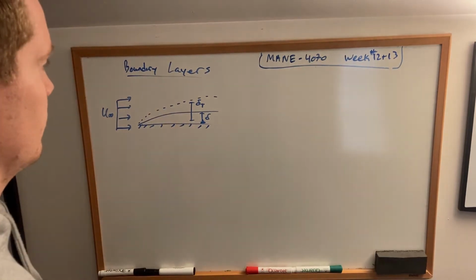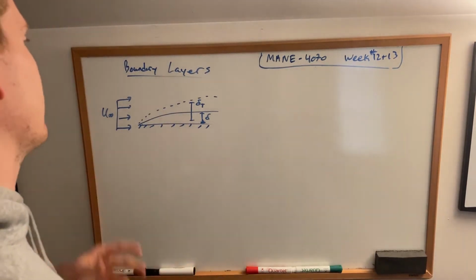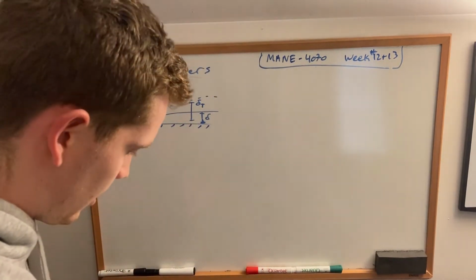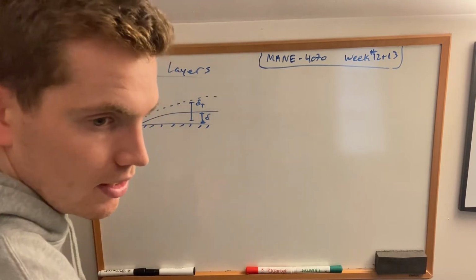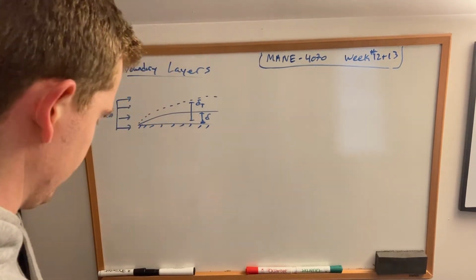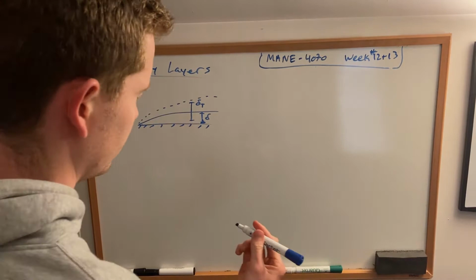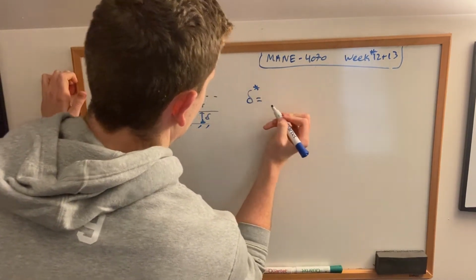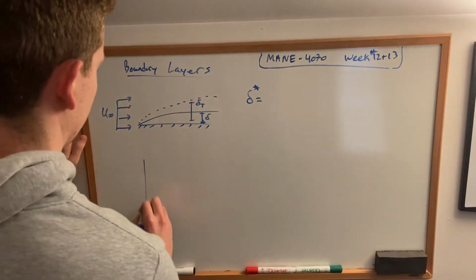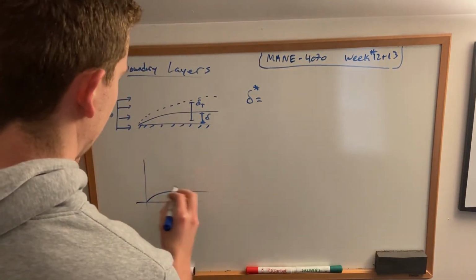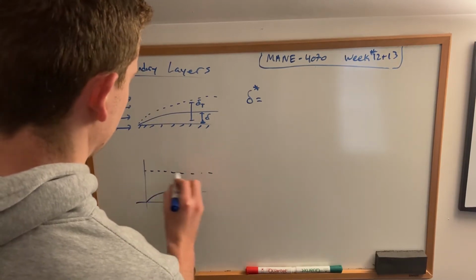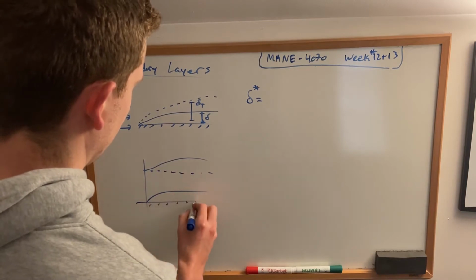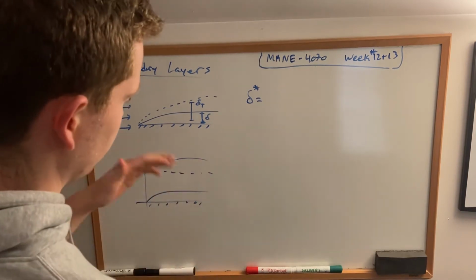So generally when anyone mentions boundary layers, you have this immediate diagram in your head, something growing over time or over distance. And from that, we did a quick review of a couple equations that were touched on, I believe, in homework 9, which was our displacement thickness, which is the displacement caused by a boundary layer at some offset. Because there's a loss of momentum here, the streamlines then have to deflect upward.